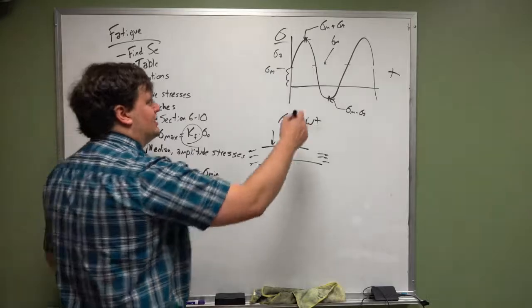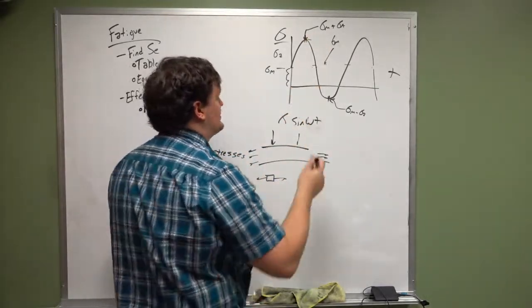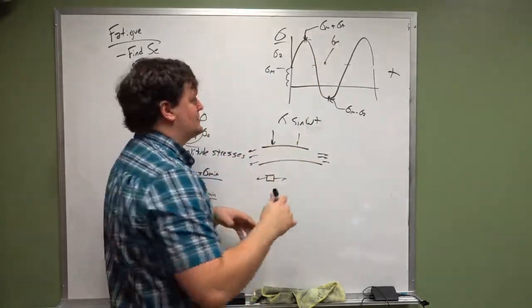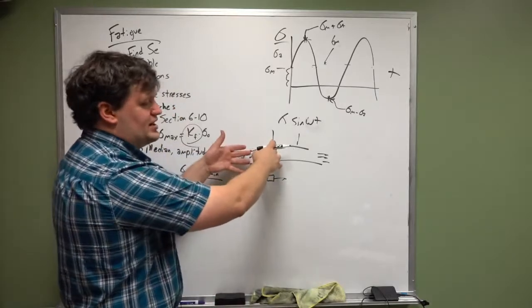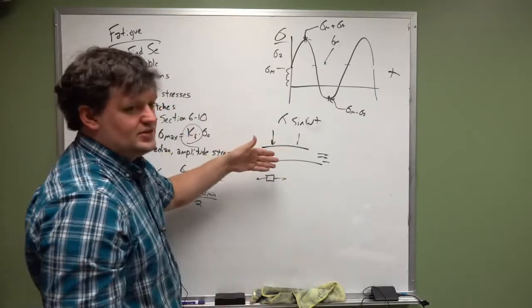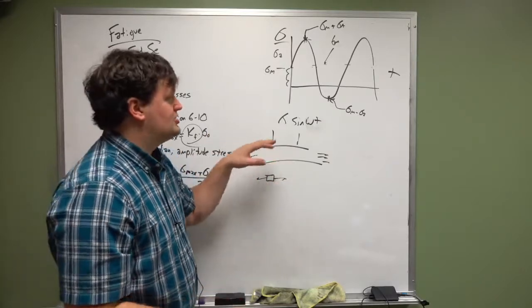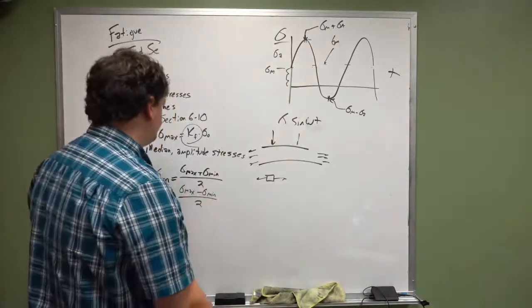But you would have to calculate what the x directional stress is, or more so what the principal stress is at the maximum loading position, and then where it's at its minimum. So when it's rotating in this direction and this is in tension, you rotate it around, and then it's in compression. When it's in compression, you're at a minimum. When it's in tension, you're at a maximum.